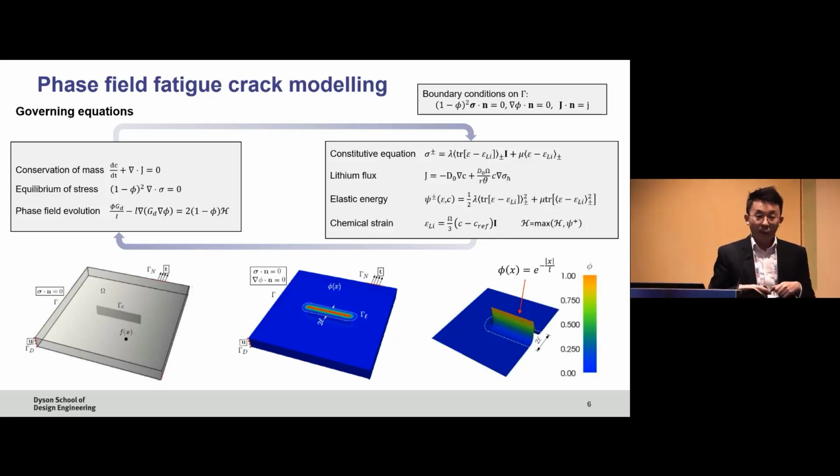So probably you've seen fatigue in a range of different applications. So metals, for example, if you take a paper clip and you bend it back and forth, you will fatigue the material as it work hardens and you decrease the crystal size in your material. And a similar sort of effect happens in lithium-ion batteries, that as you stress your material over time, you will change the fracture toughness properties of that material. So phase field modeling allows us to understand how materials crack over time.